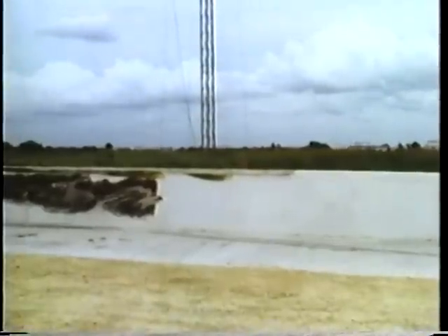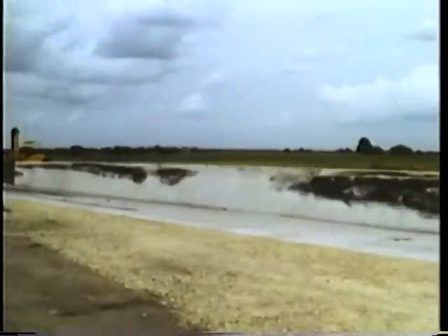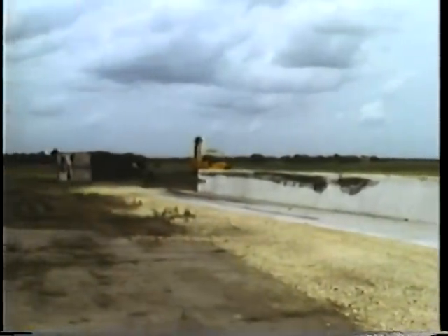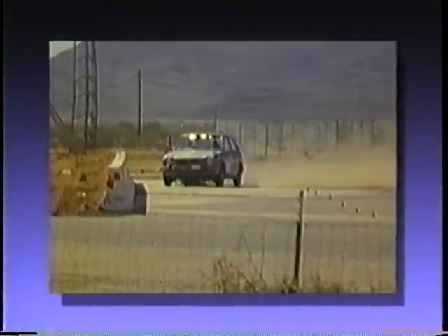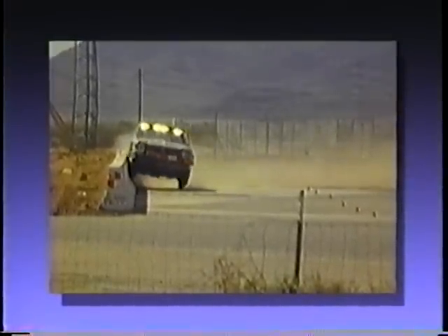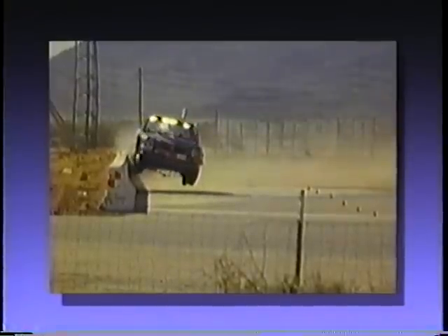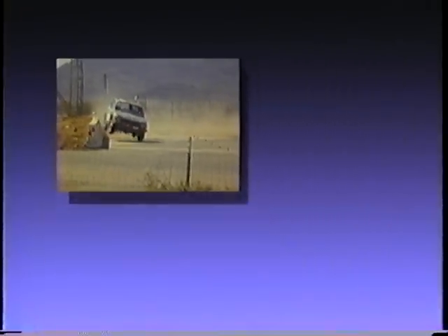Damage to both test installations consisted primarily of scuff marks, scraping, and gouging of the concrete. The bridge railings would still be effective after these very severe collisions. Each of these barriers has its own advantages and disadvantages. The barrier with the least vertical face, the New Jersey barrier, causes the least amount of sheet metal damage and has the best occupant response.